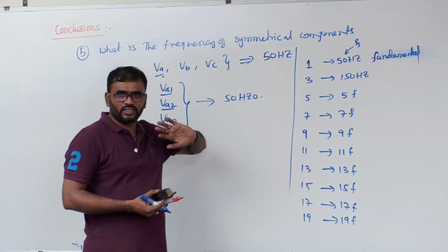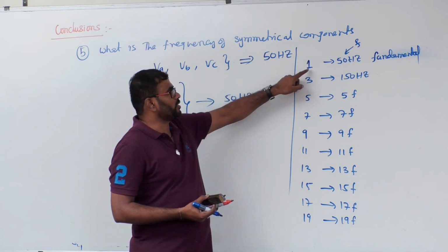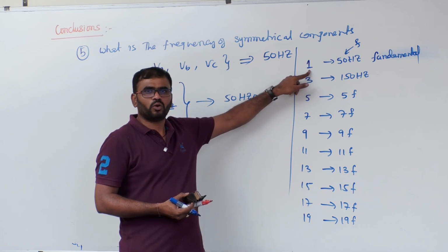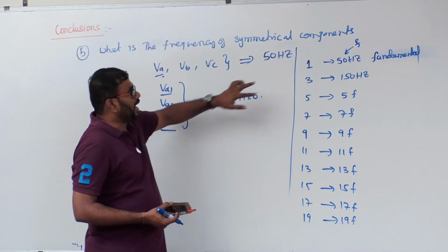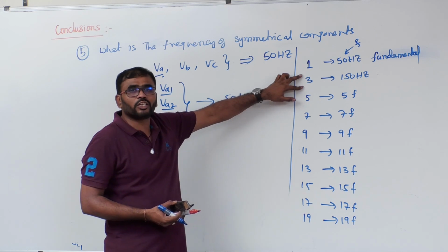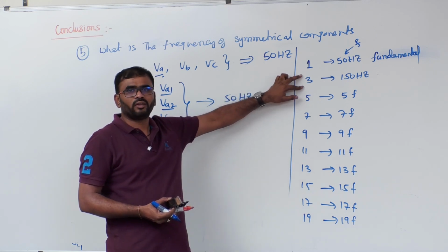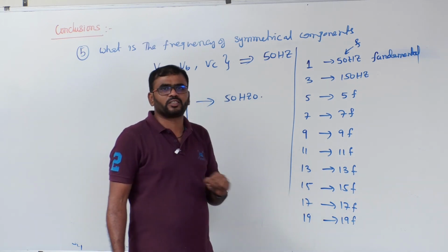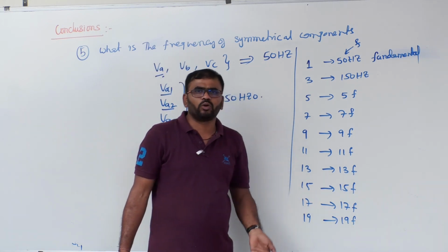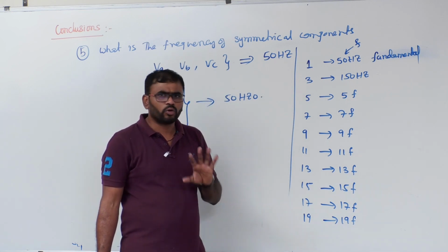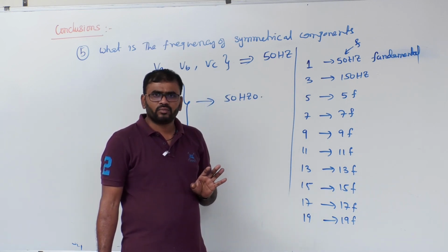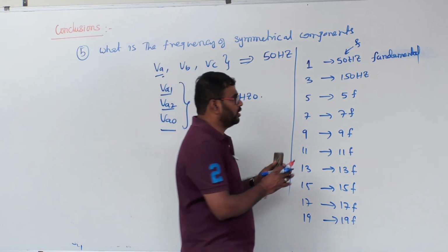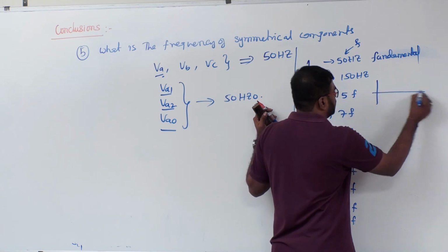Now just see, sir, the positive sequence is the same as the original balanced phasors. That means the positive sequence and the fundamental have the same relation, strictly speaking. Next, the third harmonic is just similar to zero sequence components. Clear? See, if the third harmonic voltage in A phase is V, what is the B phase third harmonic voltage? Same V. No difference. Clear? What about the C phase third harmonic voltage? Same.